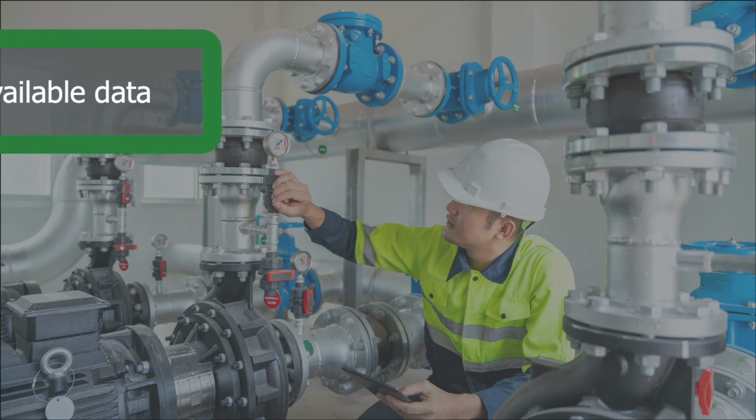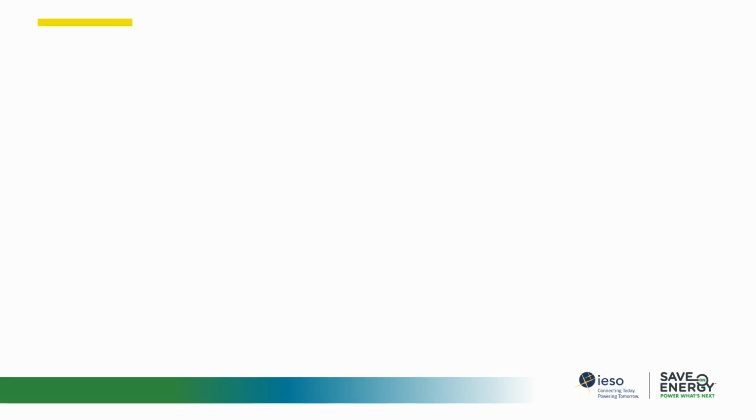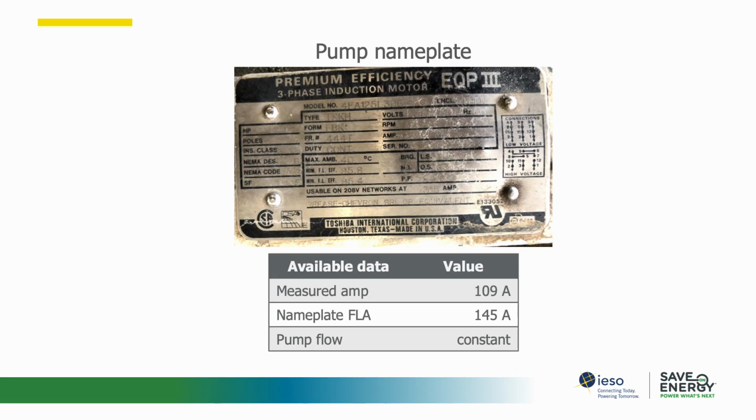Let's start by assessing the data available to develop the baseline and estimate the savings. While we only have a few amp measurements for the pump and motor nameplate data, we know that the pumps are running continuously. Although the valve positions vary, the three-way valve means that the pump flow and therefore the motor load are relatively constant. We can therefore expect to develop a reasonably accurate baseline from the spot amp measurements.